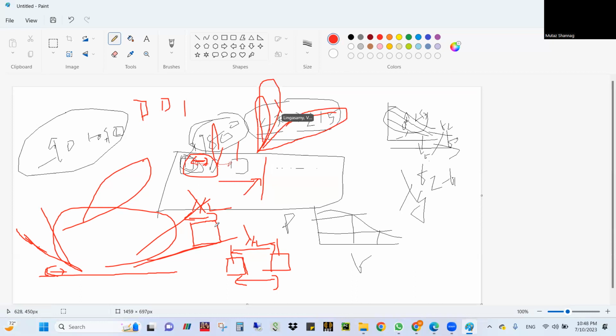So in order to suppress that, we apply several algorithms. It is like two things. One is, you have to optimize the spacing between the elements. Another one is optimizing the weights in such a way that you should not get these grating lobes or side lobes. You will only get the beams like this. That's it. And also, see, it is after all a dipole, maybe we can say monopole, so it will have some kind of back lobes, right? So the moment you steer the beams like this, these back lobes will shoot up here. That's why we have to optimize these things.